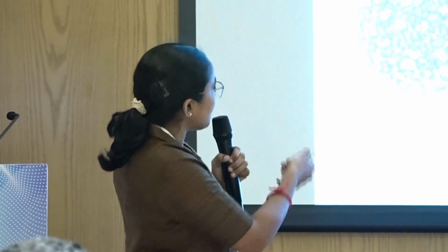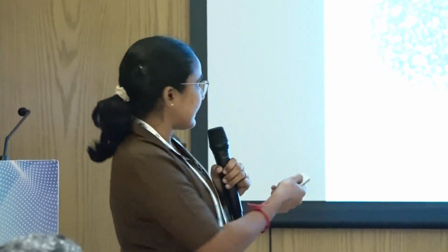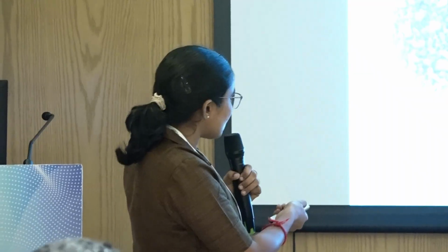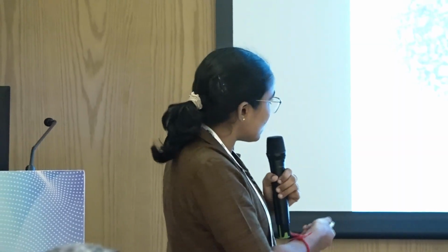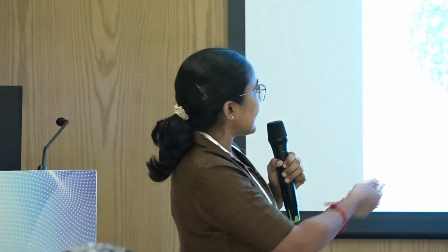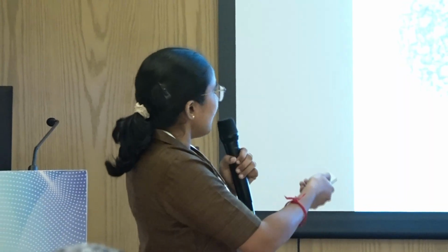But as the degree of crushing increased, the particle size decreased to a very small size, and they occupy the pores internally and become uniform, not like the segregation of sand and mica particles. So when the particle size of mica decreases, the detrimental effect of mica tends to decrease.